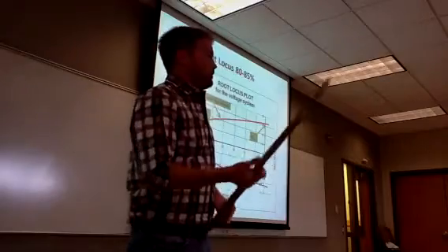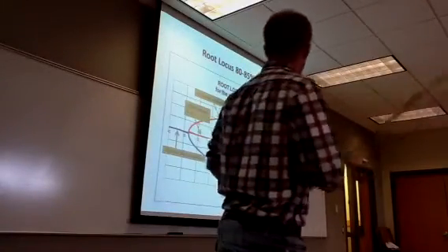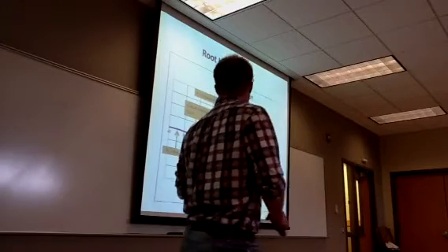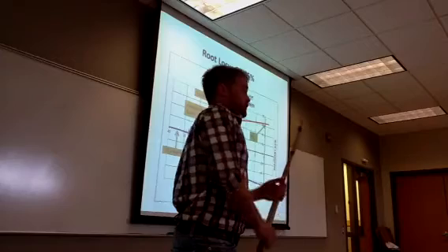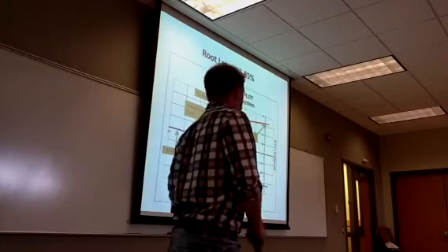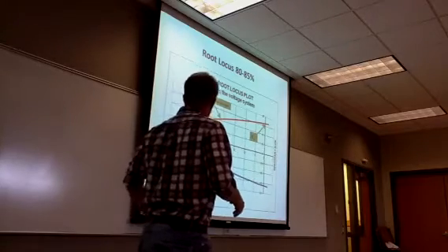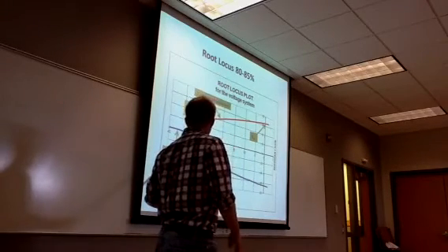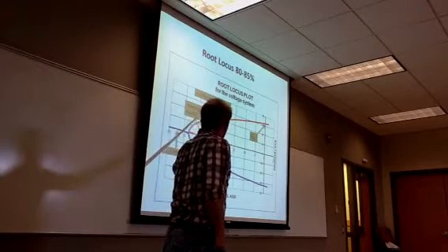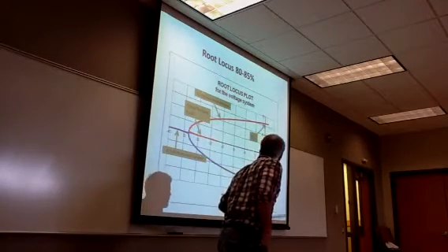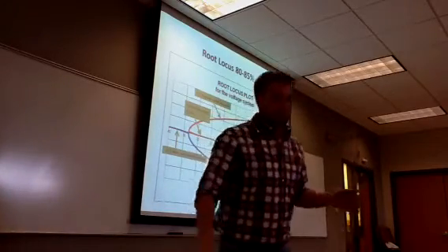So from the parameters we found from the Bode diagram, we plugged in and came up with a root locus. From the root locus, we had two different root loci. This one in particular is for the proportional only. As you can see, we got the overdamped Kc's, the critically damped, the underdamped, and then the ultimate, which is on the y-axis.